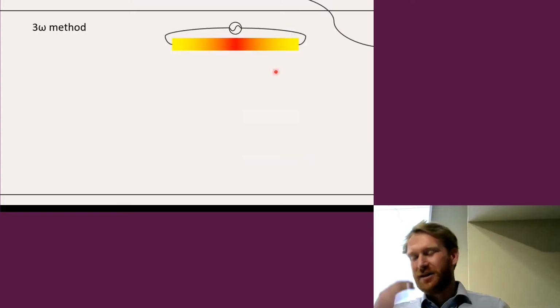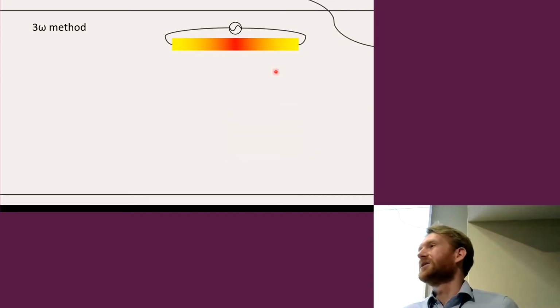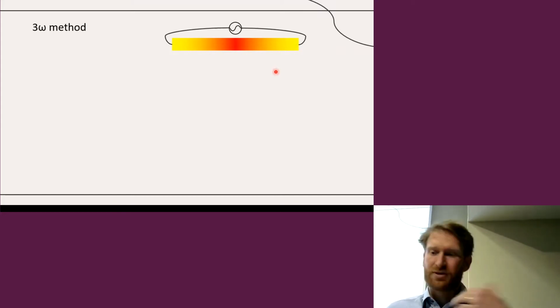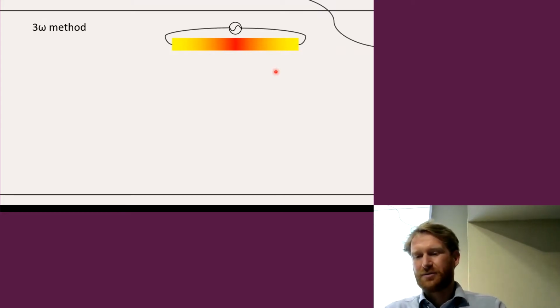So they are very easy measurements to set up. Now, again, because we already have a lot of understanding of this measurement of the electronic transport, we can use all the knowledge from the electronic transports to measure the thermal properties here. And the most common way to do that is the 3 omega method, which you can do in several ways. But the easiest way is the self-heating.